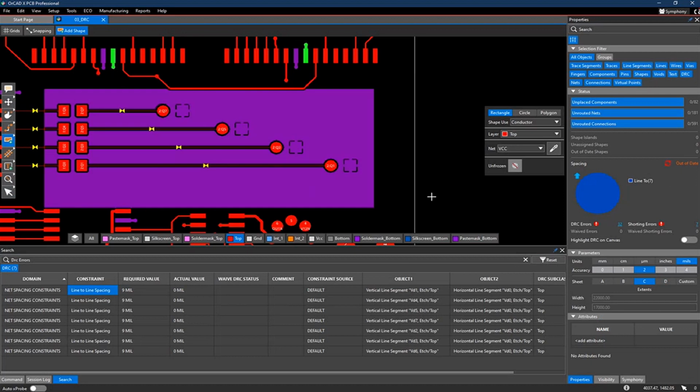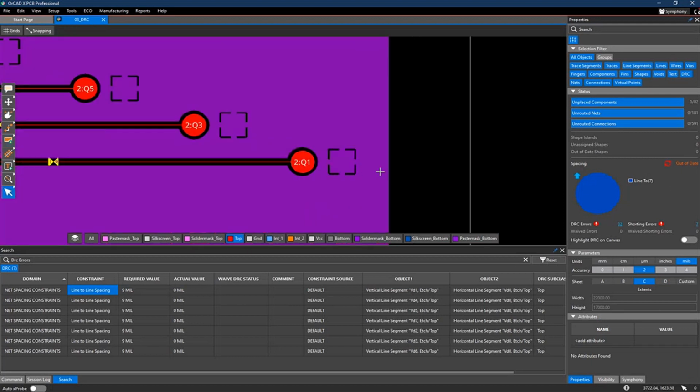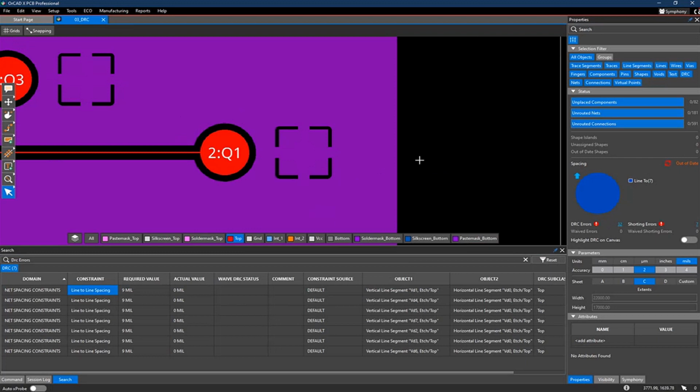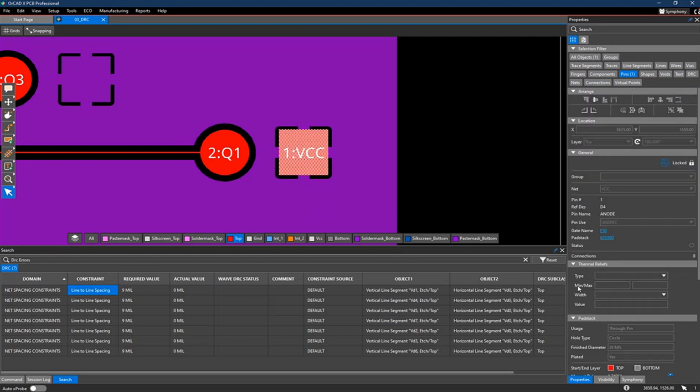And you see, like in the old PCB editor, the basic settings of the shapes come from the global shape, dynamic shape parameter. What I want to show you now is a thing regarding the thermal tie. We have a thermal tie connection like this here. If I want to change this for one dedicated pin, I can directly do it here. I go to pin properties, and then, for example, I have the thermal reliefs for that pin here, and I can directly change it maybe to full contact. Very easy to use, no need to go into edit properties and select one of these fancy dynamic shape properties.